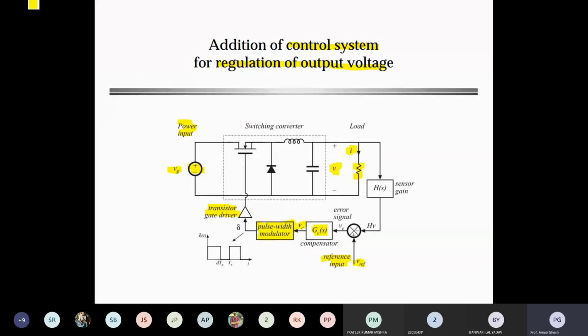So the expression of TC is, sorry, I was wrong, it is not V0, it's V0 output max. V0 max minus V0 min, whole divided by V0 nominal, into 1 by T max minus T min, whole multiplied by 100%. The unit will be per degree centigrade.